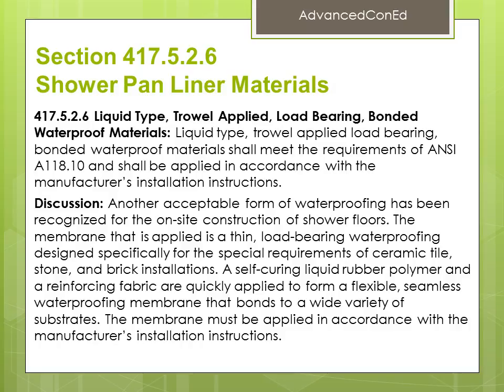Discussion. Another acceptable form of waterproofing has been recognized for the on-site construction of shower floors. The membrane that is applied is a thin, load-bearing, waterproofing design specifically for the special requirements of ceramic tile, stone, and brick installations. A self-curing liquid rubber polymer and a reinforcing fabric are quickly applied to form a flexible, seamless, waterproofing membrane that bonds to a wide variety of substrates. The membrane must be applied in accordance with the manufacturer's installation instructions.